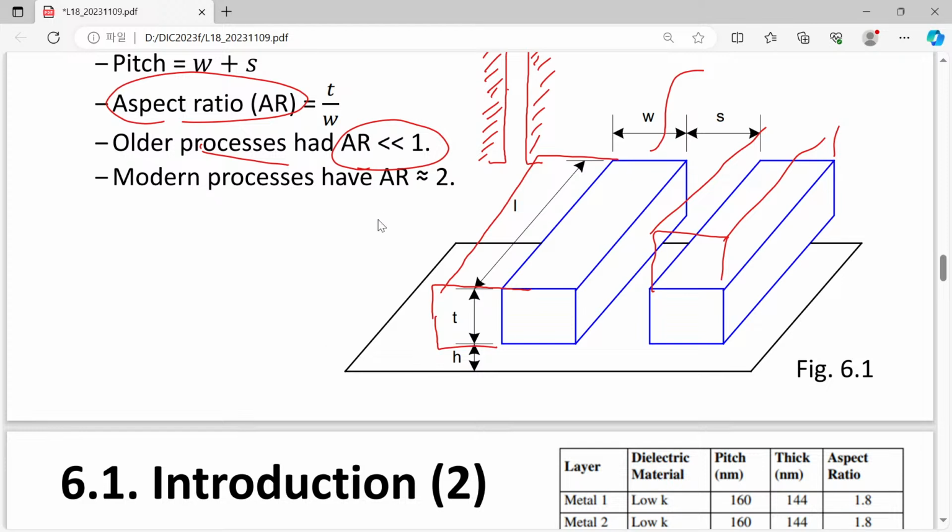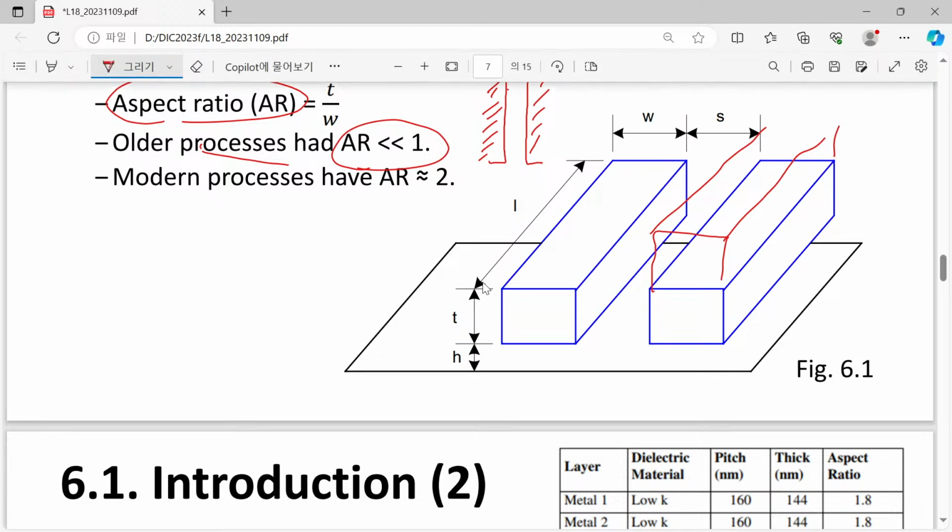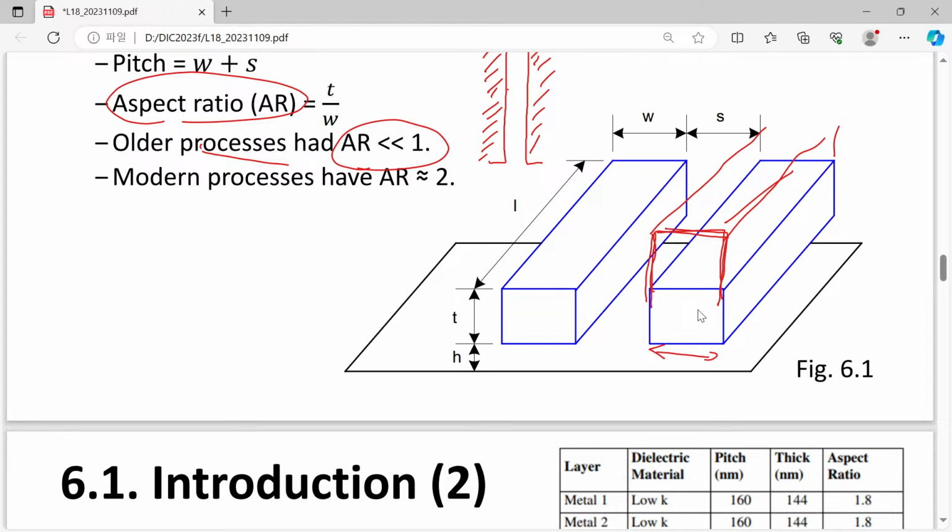So we don't like spending more area on the same metal line. So in order to keep the resistance at a reasonable level while scaling the size, this is one way we can do it. Make it tall. Then with the same area, we can introduce higher conductivity, meaning lower and lower resistance. Okay, are you with me?